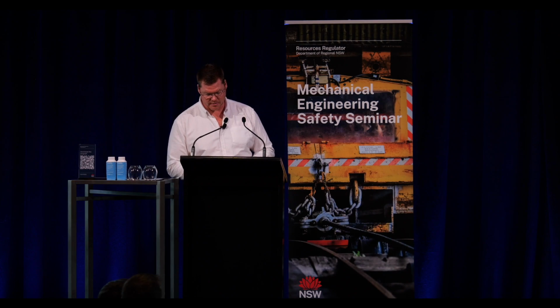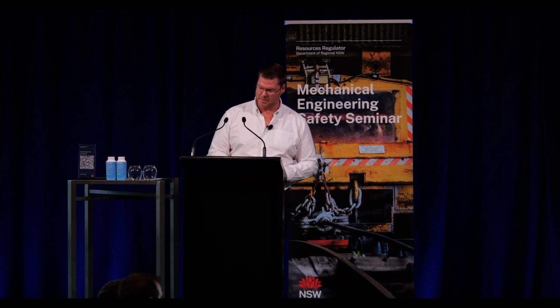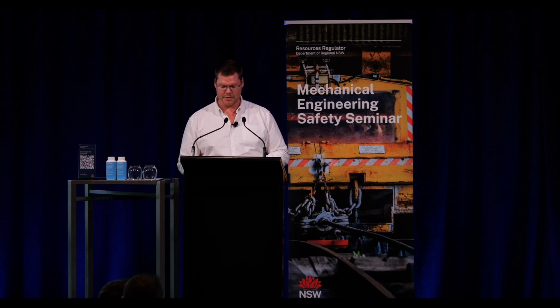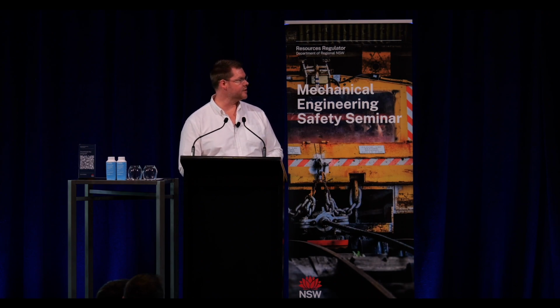So to minimise these risks, it's important that we regularly inspect and maintain the deflection sheaves, that we ensure that we've got proper sizing and alignment of loading, and we follow the safe operating procedures to ensure safe and efficient use of those sheaves.